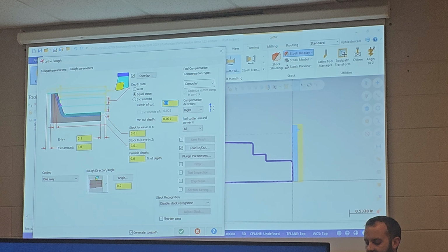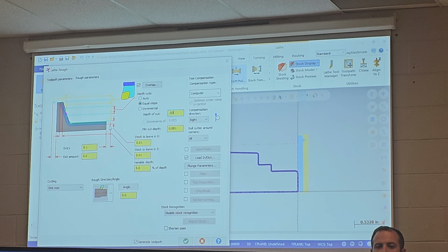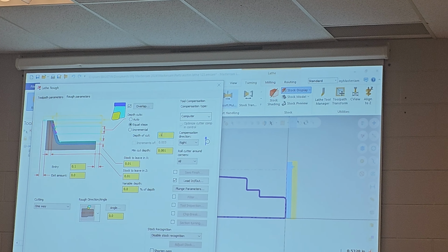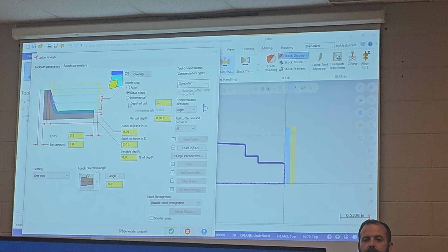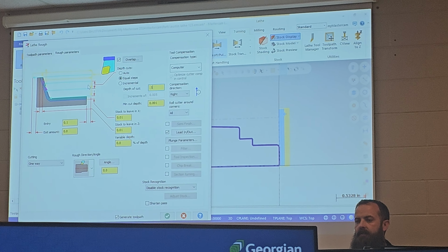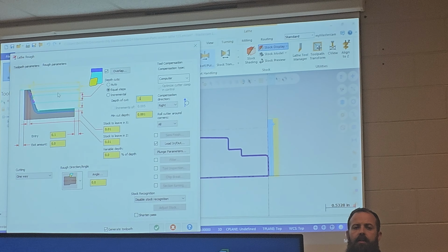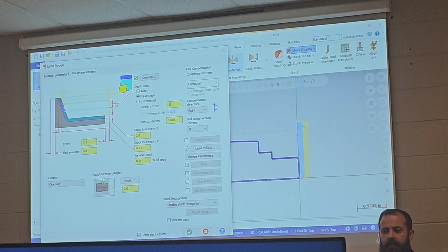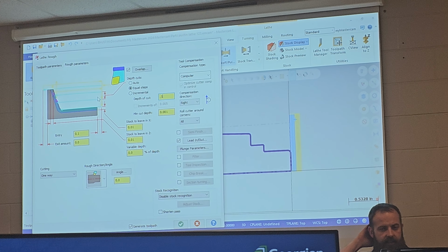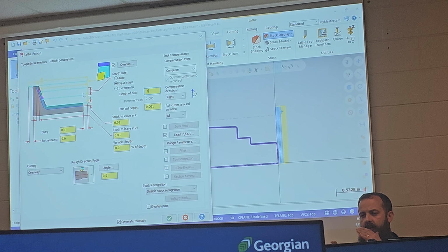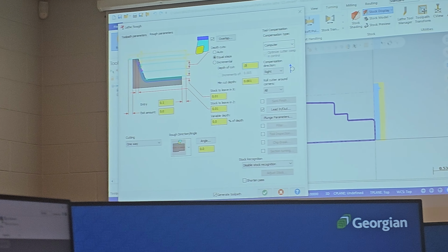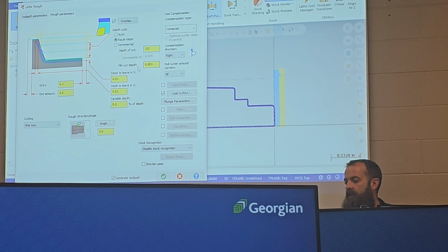I would like to take a depth of cut of no more than about 30 thou. That one is important. You'll notice before I did that, it said 0.1. That is like 3 times too much. Okay, it's not that an industrial lathe can't do that, it's that the tool posts on those bosses are reasonably light duty and you don't want to overflex it. And you'll start to see weird things happen, the tool will move around a bit, you can turn the post, you can break stuff. Let's keep it conservative for the first one, we'll say 30 thou of depth,